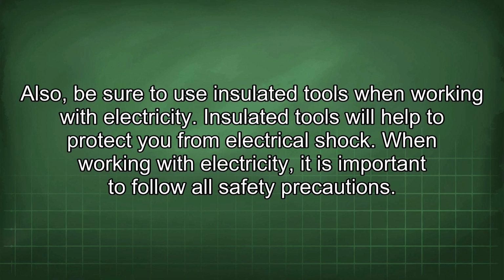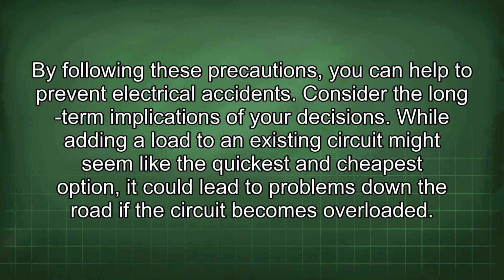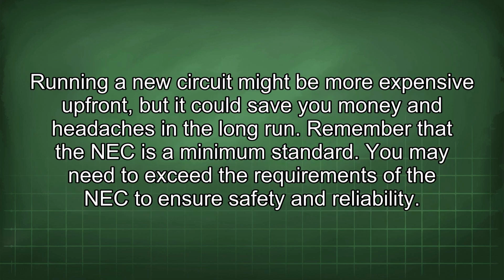When working with electricity, it is important to follow all safety precautions. By following these precautions, you can help to prevent electrical accidents. Consider the long-term implications of your decisions. While adding a load to an existing circuit might seem like the quickest and cheapest option, it could lead to problems down the road if the circuit becomes overloaded. Running a new circuit might be more expensive upfront, but it could save you money and headaches in the long run. Remember that the NEC is a minimum standard.